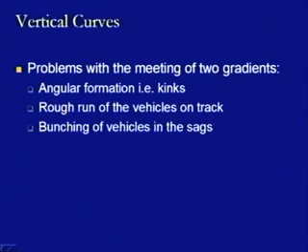they can be pushed inside, and when there is a bunching of the vehicles, then those connectivities will remain inside of the wagon itself, and there will be very little distance left between the two bogies. So, this is another effect of the sag or of the gradients which have been provided, and this may also have its safety implication in the sense that as we are moving towards the sag, all the vehicles or wagons will be trying to hit it.